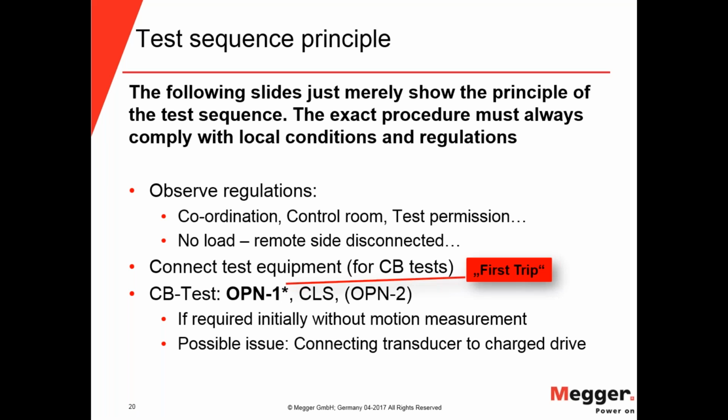So one important thing is that this open that you do, the first one, is actually your first trip measurement, because this breaker might have been in service for a long time, not operating at all.